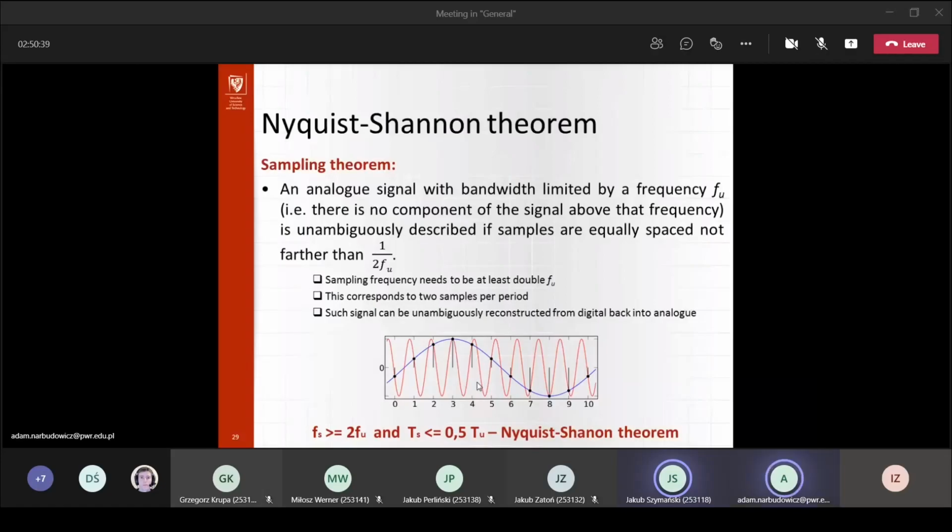But if we have aliasing, then what we see from the, I think it's called sin x over x, for example on an oscilloscope, would change with the sampling frequency. Yes. So basically, when you increase the sampling frequency, you get rid of the aliasing.